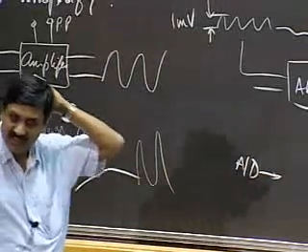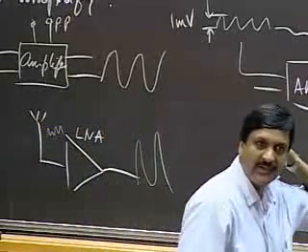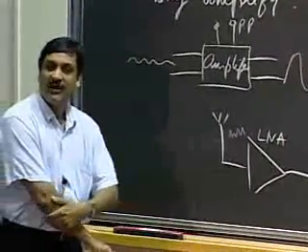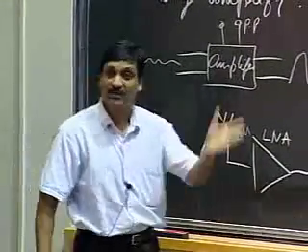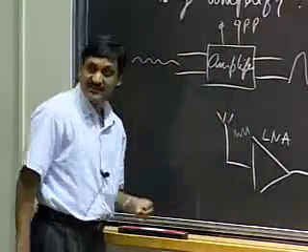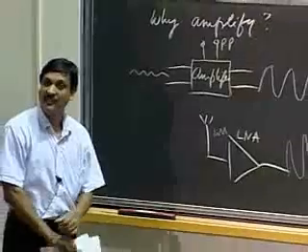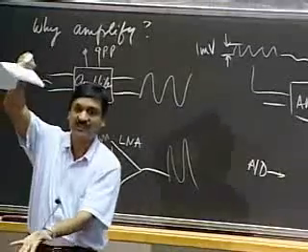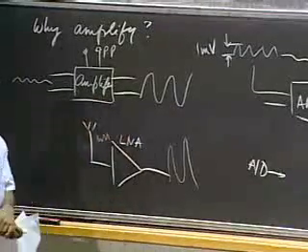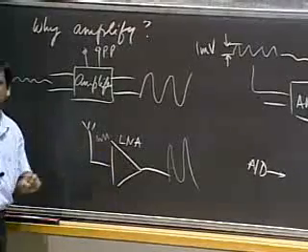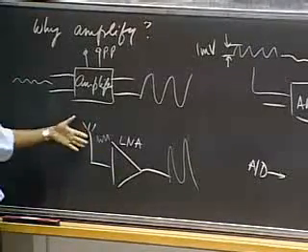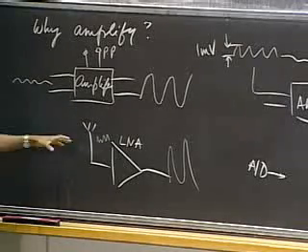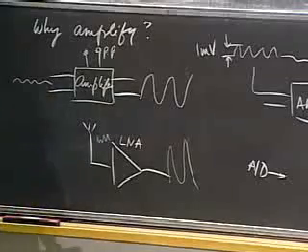I recall last week, I asked somebody in class how we would transmit the signal from point A to point B without being impacted way too much by noise? And he said, oh, go digital. Good point. If I go digital, I can transmit the signal without noise being a real factor. But then the analog to digital converters need the signal strength to be a given value before they can chop it up into digital levels. So an amplifier is very fundamental. In this case, what may be a signal of a few tens of microvolts has to be amplified to some large enough value that it can be further processed.